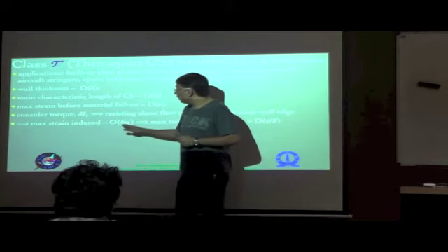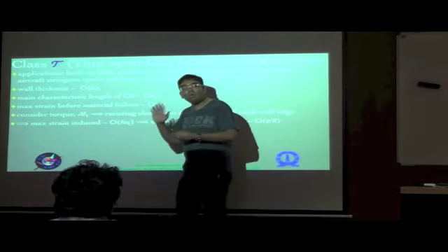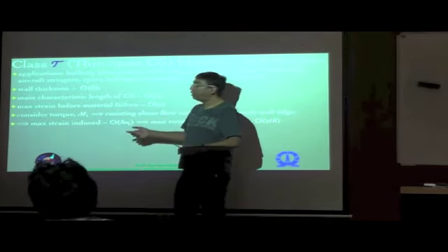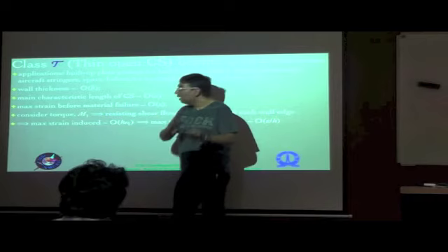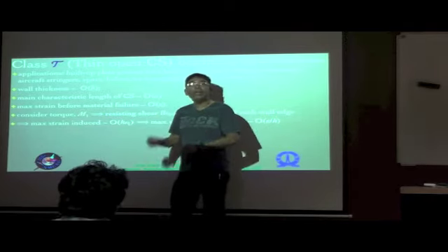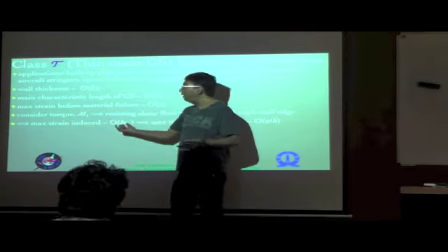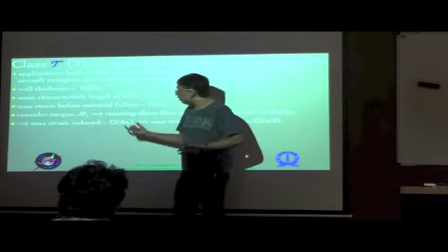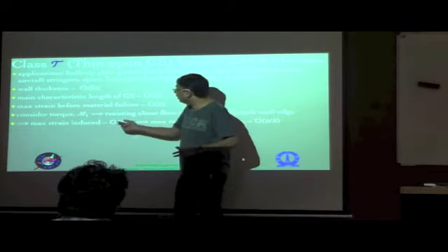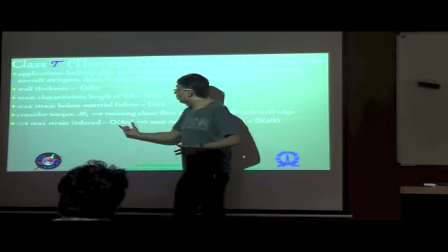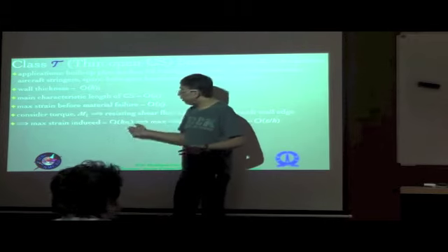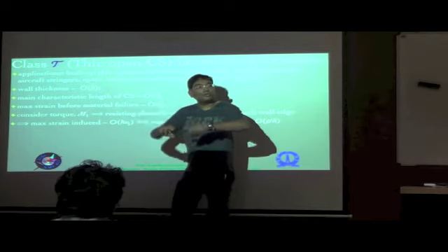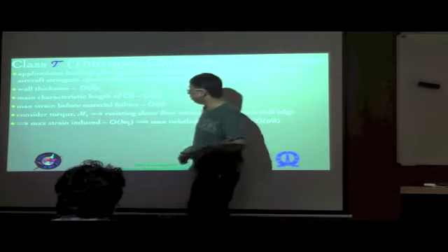This is of course something which we can intuitively see or from the kind of knowledge that we have gained, but we can and will derive the actual expressions for the strain, and there we will actually show that it indeed is of this order of magnitude. So for now, you just take it for granted either from your intuition or from my explanation here that the maximum strain induced is of the order of h times kappa 1 because it is proportional to the moment arm and it's proportional to how much twist per unit length the cross section is undergoing.